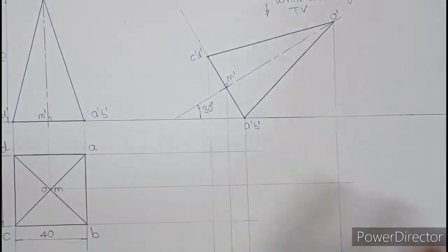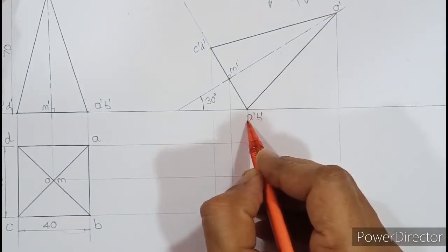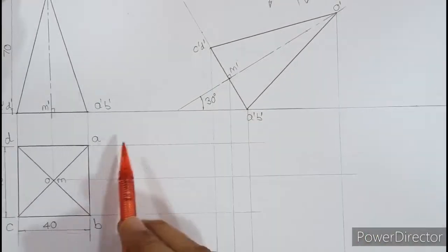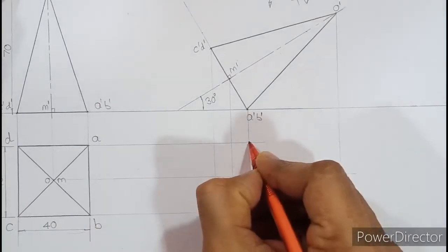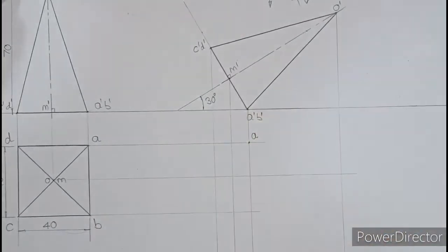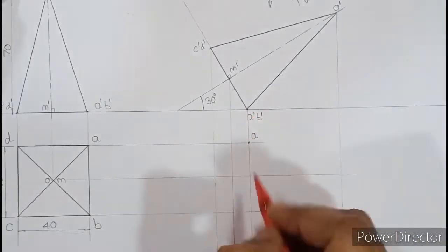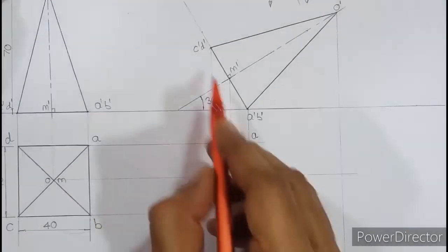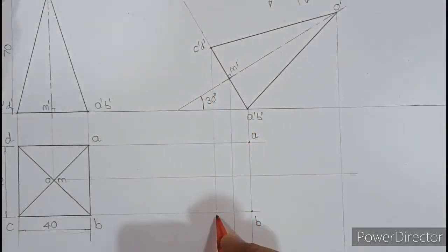Okay, so now after you're done with all the projections, what you should do is, from the third diagram, see, start with A dash here, so this is the projector of A dash, and correspondingly in this diagram A is here, so the intersection of both the projectors of A, that is your point small a, and that will move above. Similarly B dash is here on this projector, and the next point B is here, so the intersection of both will give you B, so write outside like this. C dash is here, so this is the projector of C dash, and corresponding C is here, so you'll get C over here.